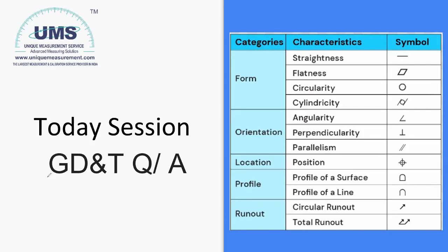So when you take those three datums which are identified in the feature control frame as datum references, you will get three mutually perpendicular planes, and that is called the datum reference frame. I'm just explaining it orally because there are a few more questions. Maybe after finishing these questions, I can take an example for multiple datums and explain it to you.